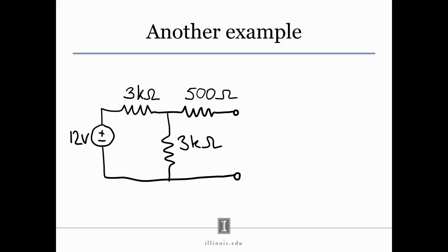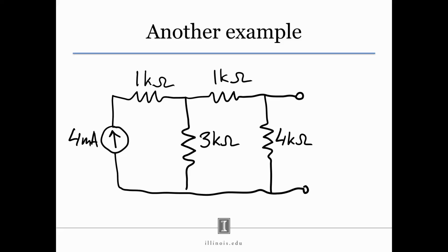And by the way, here's another one. This time we'll have a current source. A current source right now is a little bit of an abstraction. We understand a voltage source as a battery, but what is a current source? Various things can behave like current sources, where you can buy a current source, which is going to be like a box, useful, for example, for driving lasers. Anyhow, it's easy to draw a current source on paper, and why don't you analyze this circuit and find its IV characteristics and compare to the previously analyzed circuits above.